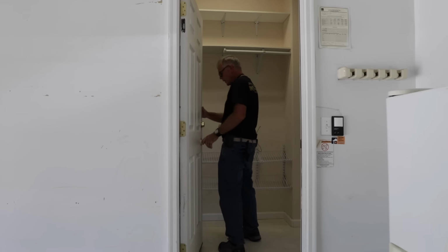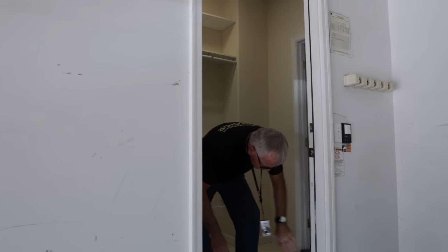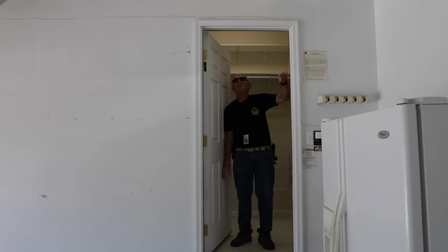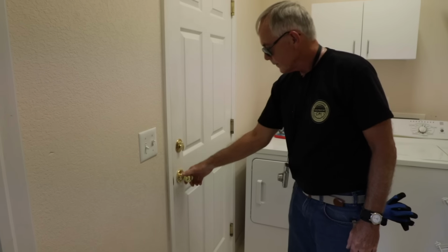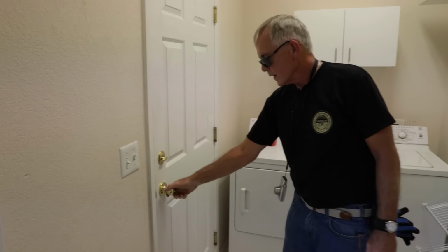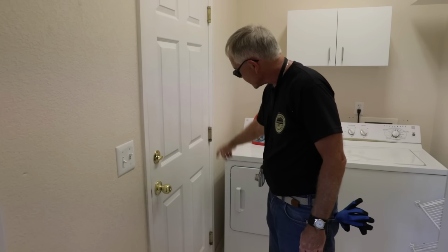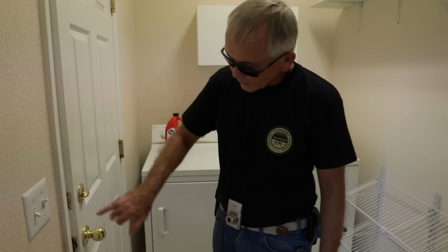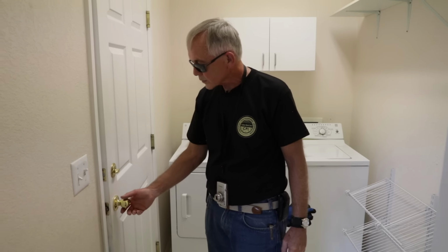Okay. We're going to come on in here and first of all, let's check our weather stripping all along the jamb. Take a look at our threshold. Everything looks good there. Check the deadbolt first, it's good. Lower lock. Takes a little coaxing, but it is working. So I'm going to go ahead and just recommend an adjustment for the self-closing hinges. We want to make sure that this latches by itself. We don't want any gaps here that would allow any vapor or smoke into the house from the garage.